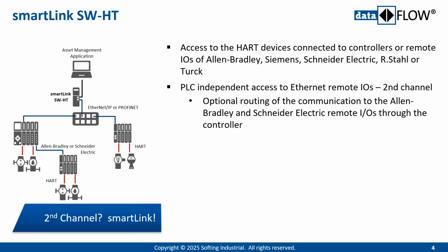For other control vendors, we have optional routing through the controller, so that's available for Allen Bradley and Schneider Electric. For Siemens, we don't support that routing, so the SmartLink SWHT has to be connected directly to the Profinet network.